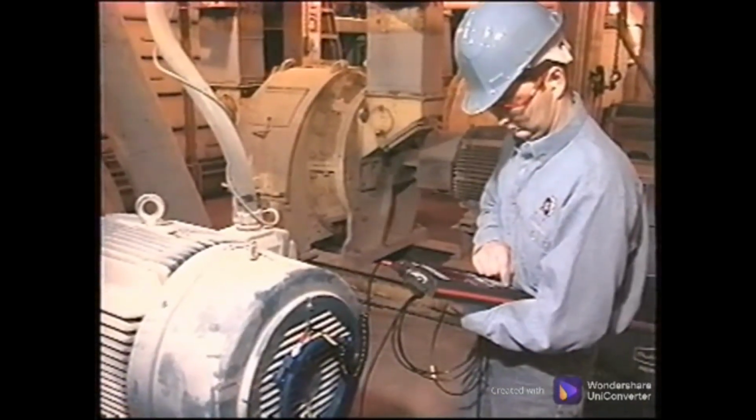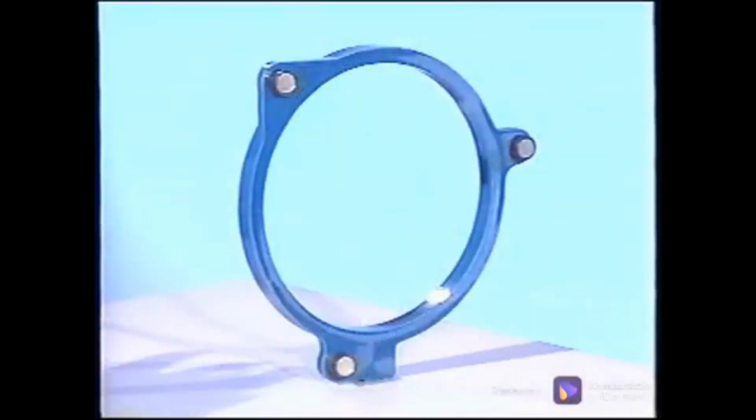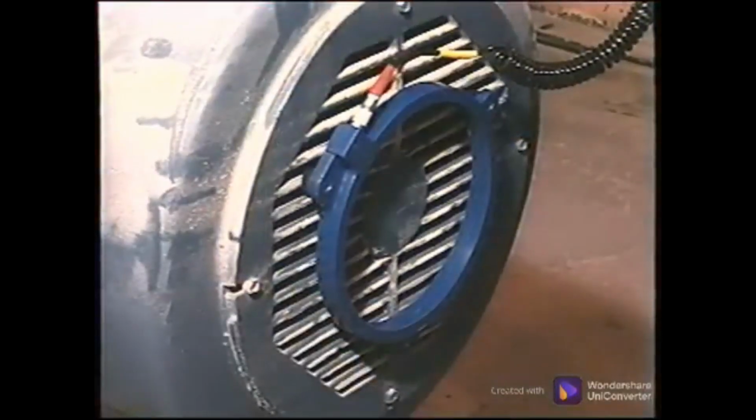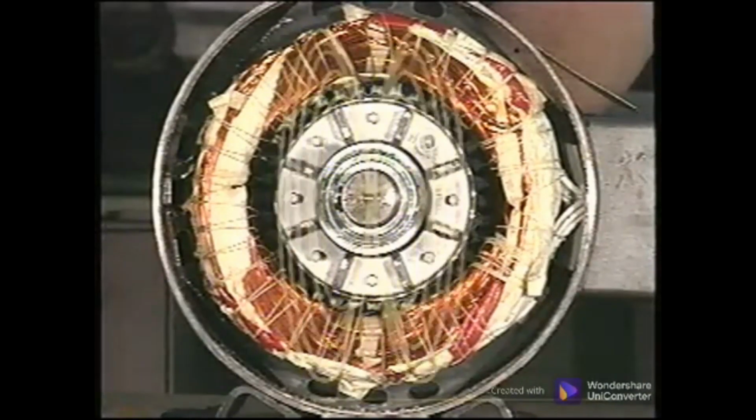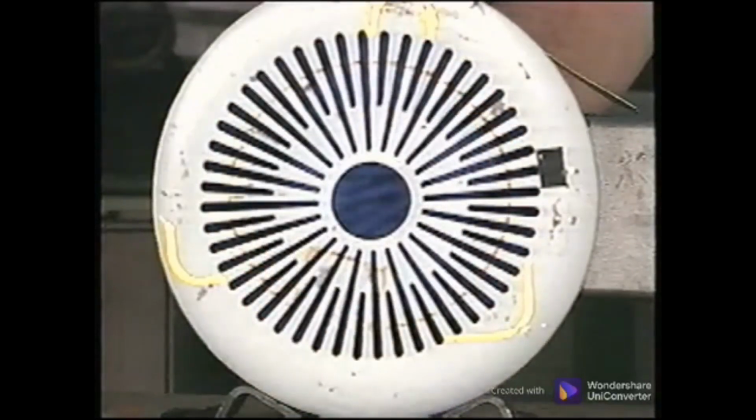Flux measurements are made directly on the outboard end of a motor. Since the flux coil has magnetic feet, it can be placed on the end bell of most motors. This measurement depends on the flux field, so small changes in the motor flux affect the resulting data, and small changes in the coil position also affect the data.